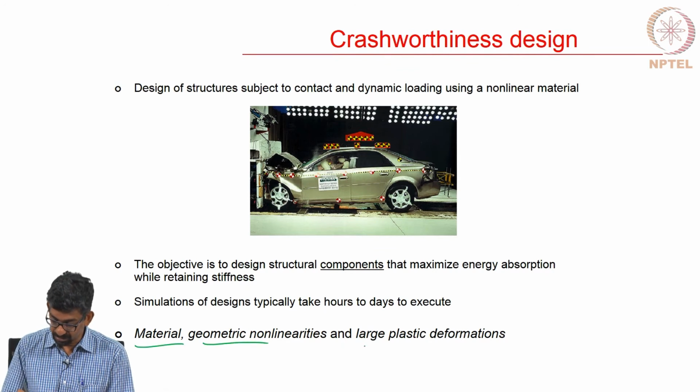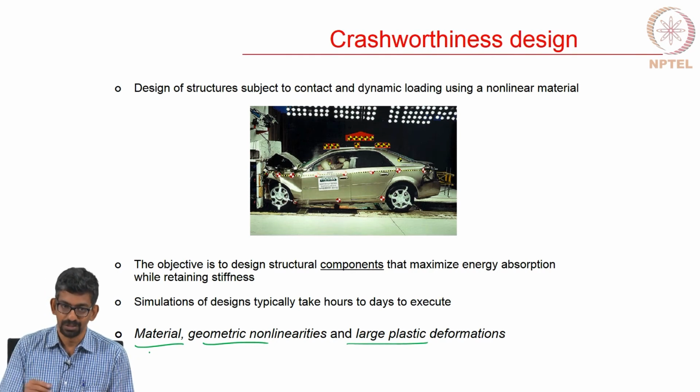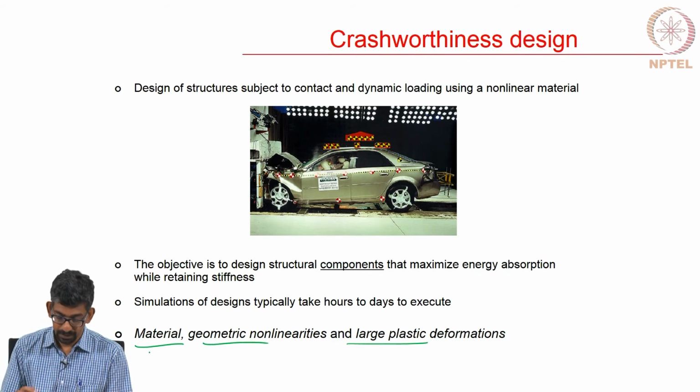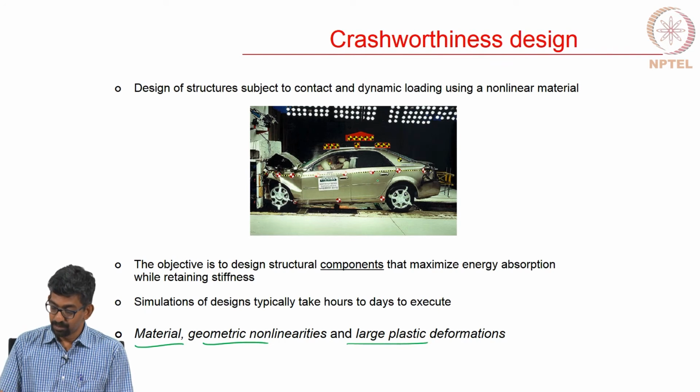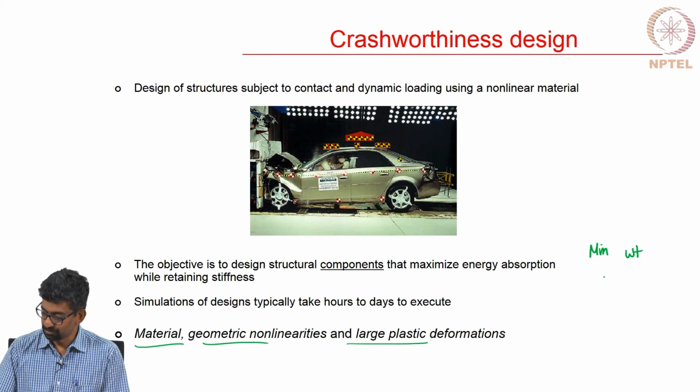of material, geometric and large plastic deformations. Material nonlinearity means large plastic deformation, and there is also boundary condition nonlinearity, meaning you start with a boundary condition, but during the crash the boundary condition changes. So, this is an interesting problem because you want to minimize weight, at the same time you want to increase the energy absorption.